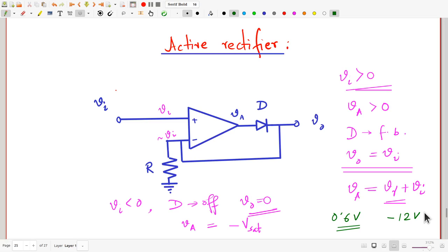And it is tiny as long as your input signal frequency is small enough. But if your input signal frequency is of the order of, say, hundreds of kilohertz, then the time period for the entire signal is of the order of tens of microseconds. So 25 microseconds becomes a huge time interval for this to work.